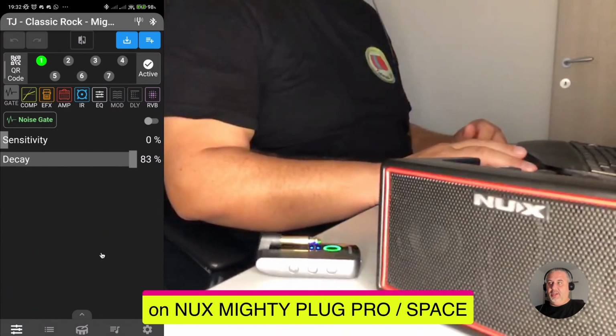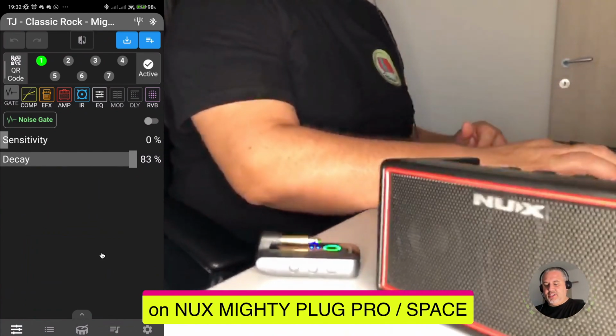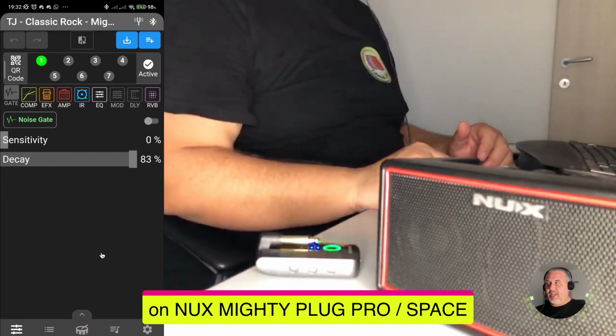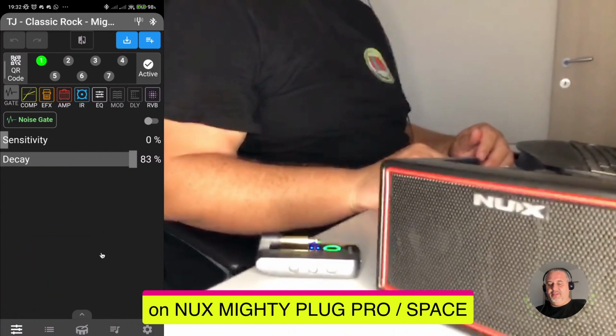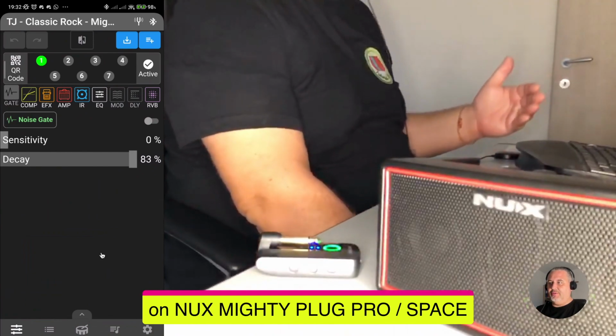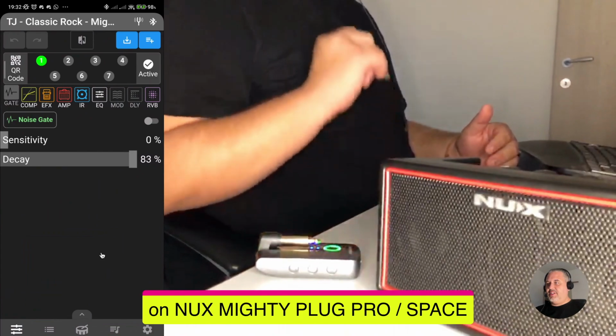Also, another warning you will find: it's possible that you run into this situation, and that is the reason why you see that in the effect chain the noise gate is turned off. We found out that in particular when you activate many effects, or you keep the volume very high in different blocks in this chain, the device starts hissing.